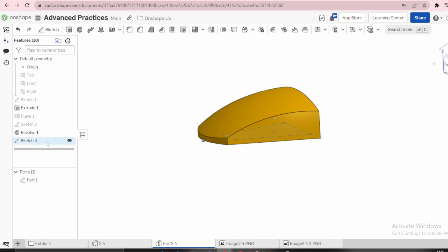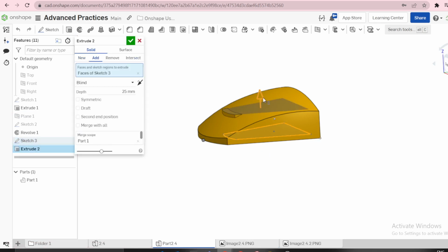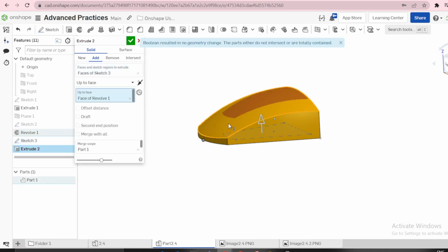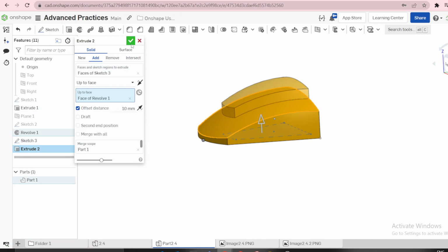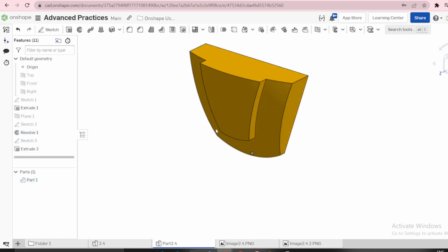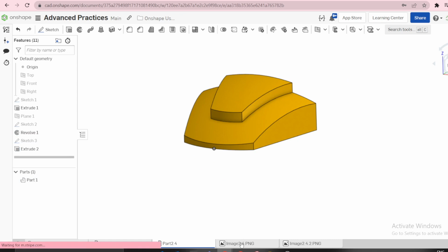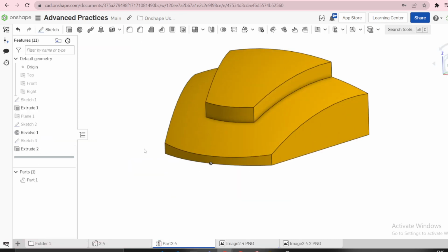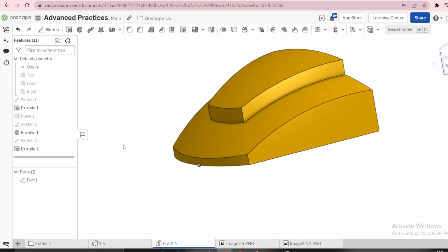let me illustrate only 2 ways. I can extrude this sketch, okay, like that. I can extrude up to face, this face, offset, can offset by 10 opposite direction. That's one way, yeah, of creating that top section, this boss here. Okay, that's one method of doing that.